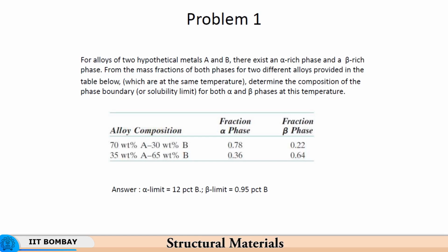For instance, tool steel has a number of hard phases which are present at room temperature, and these hard phases do not soften even at high temperatures. As a result, the tool steel retains its sharpness and has sufficient strength even when a lot of heat is generated during machining or any other manufacturing process.